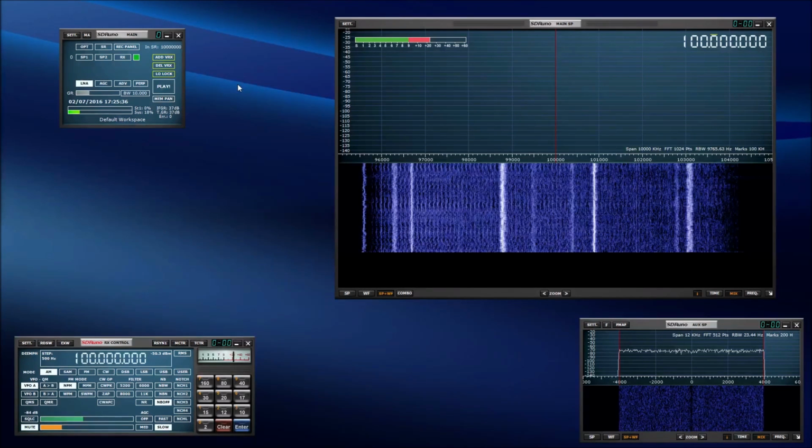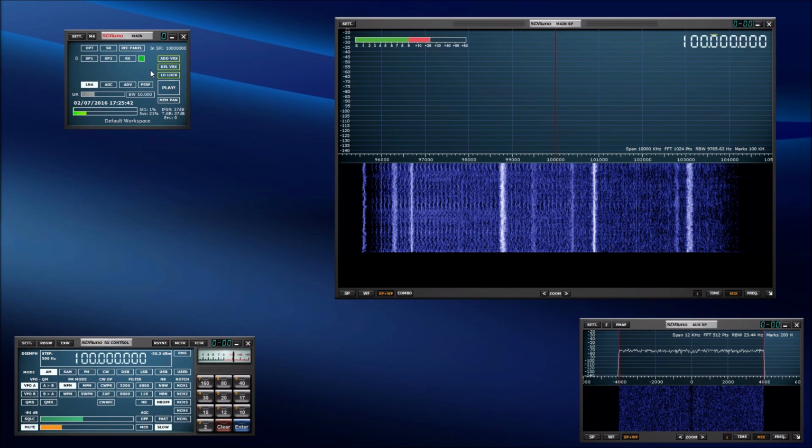Okay, so setting the sample rate. Up in the main window, anything to do with the RSP is done from the main window. Because the output of the RSP goes to all the VRXs, apart from setting the LO frequency, which is done in VRX0, everything else is done in the main window. So the bandwidth and the modes, everything is done from the main window.